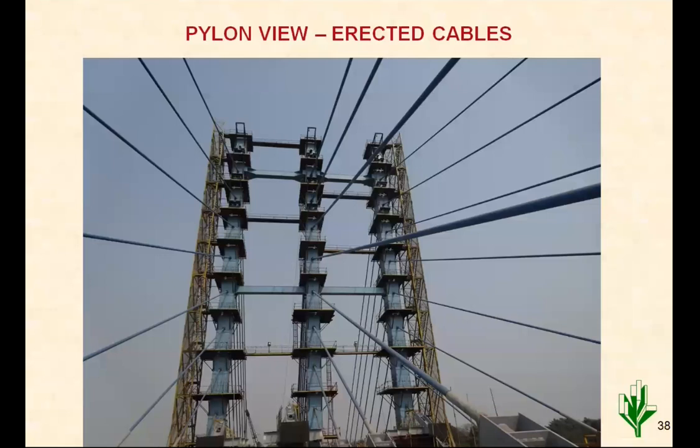Then there are cross members at 2 levels. One is this, one is at this level. Stressing is done from inside. So inside the top, I don't have the exact pictures. Otherwise, that was a very cumbersome arrangement because the space available was very less, and the stressing was done inside of the pylon. So that arrangement was slightly cumbersome. Otherwise, every other detail of this page is really very useful for any further planning.